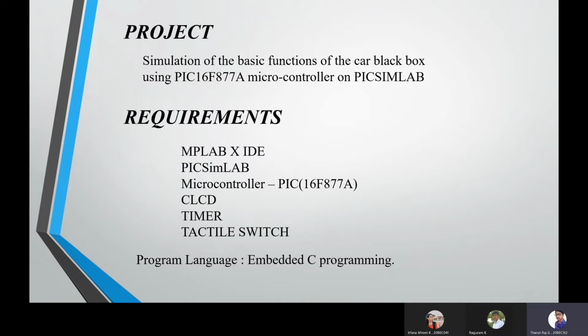To elaborate, the project is about simulating the basic functions of the car black box using a microcontroller called PIC 16F877A. And the requirements are listed here, such as the software like MPLAB X IDE and PIC SIM LAB. The microcontroller we are going to use is PIC 16F877A. Then CLCD, that is character liquid crystal display, and the timer is one of the peripherals of the microcontroller, and the tactile switches. The programming language used here is C.